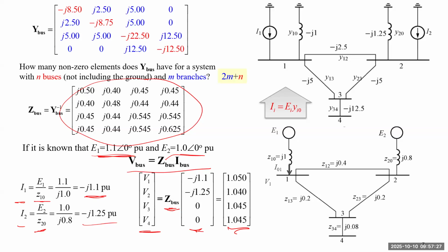Here I need to ask a question. If you take a look at the result, those values are voltage phasors, not magnitudes, because every one is actually a complex number here. But why are those voltage phasors all real? Just think about this for a few seconds. They're all real voltage, and there's no angle difference. Right, because E1 and E2 have zero angle.